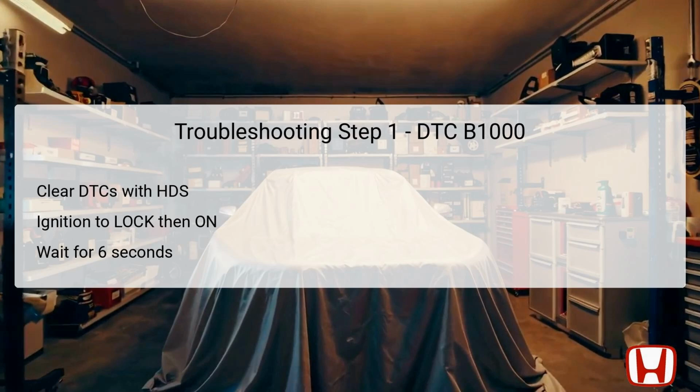The first step in troubleshooting DTC B1000 involves clearing the diagnostic trouble codes using the HDS, or Honda Diagnostic System. After clearing the codes, turn the ignition switch first to the lock position and then immediately to the on position, also referred to as the III position.